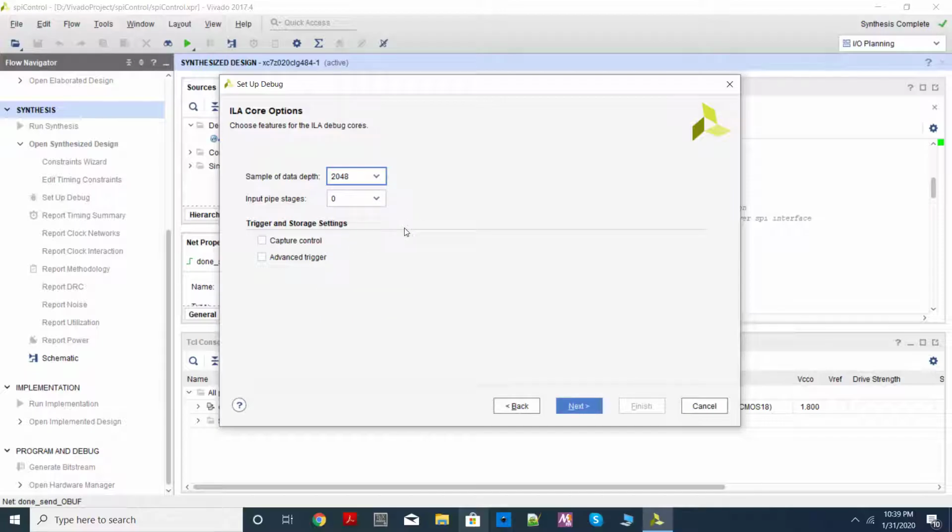Now one important thing to remember is the circuit which is going to capture this information and which will be sent to you. Okay, that circuit, Xilinx calls it ILA, which stands for Integrated Logic Analyzer. From now onwards I will be just mentioning ILA. So remember, that is the circuit which can capture the internal circuits in real time.